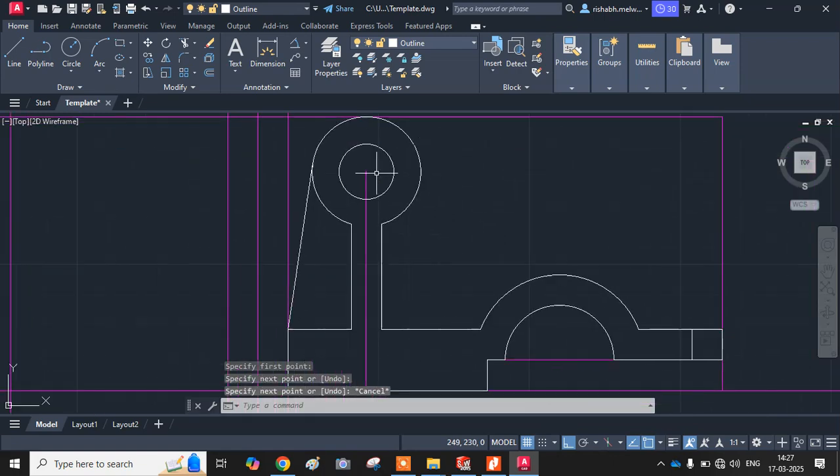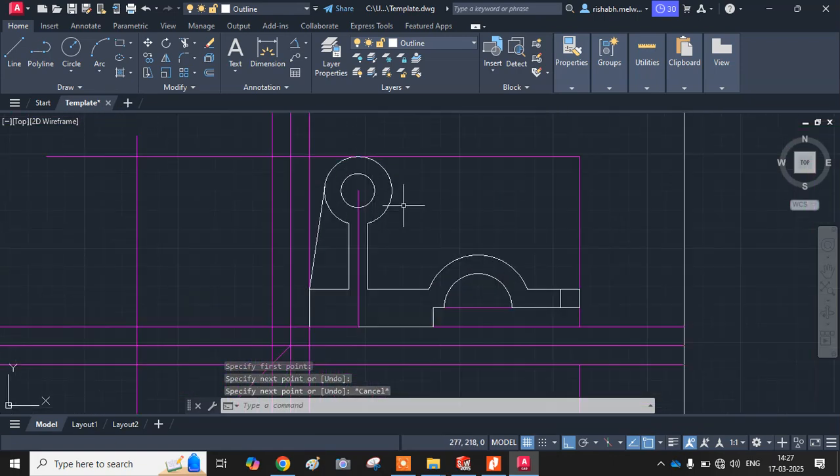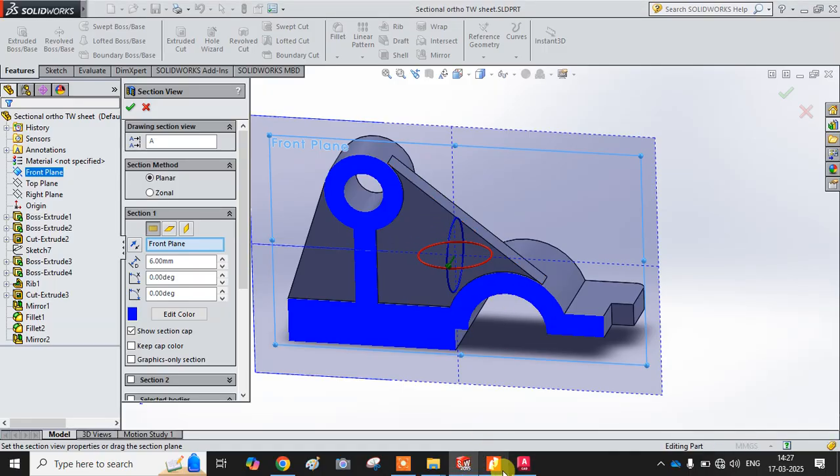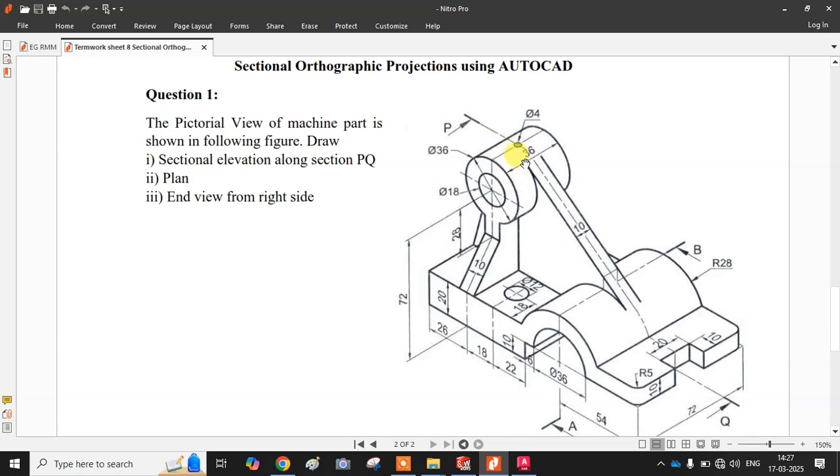Now most important part is this rib. Now if you observe this rib is basically tangential to this cylindrical portion and this cylindrical portion. So in the book you can keep the roller scale. If these two circles are drawn, you can find a circle tangent by adjusting the roller scale. But how you will draw it in AutoCAD, understand?